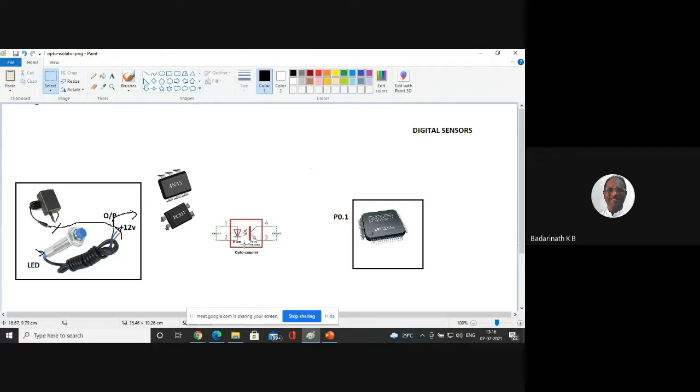The A side is not connected to the B side. There is a separation. In the relay, we have seen the concept used for separation: the electromagnet concept. Here, it's not an electromagnet concept. The concept of the photo LED and the photo transistor is used. Light is the concept used, electromagnetic radiation.